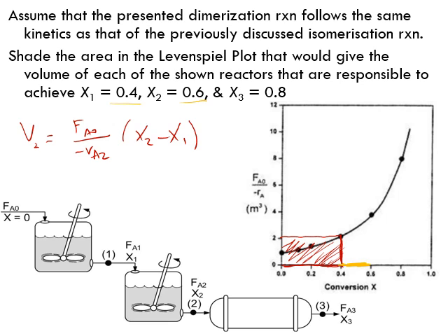What's the height? Is it evaluated at 0.4 or at 0.6? Well, it's evaluated at 0.6, because the conversion of 0.6 represents the concentration at the exit of reactor 2. This concentration helps you to evaluate minus RA2. So that's the width, x2 minus x1, and the height is evaluated at x2. Therefore this is the rectangle.